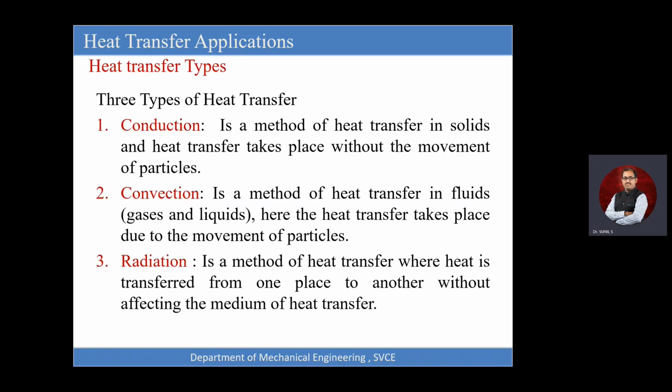There are three modes as we discussed. One is conduction. It is a method of heat transfer in solids only, right? Wherever there are free electrons, they are called good conductors of heat. You may ask the next question, why can't wood conduct? There are no free electrons. Only because of lattice vibrations, vibration of molecules, it can transfer the heat only to a little distance. By the time, this will burn up. Correct? This is not a good conductor of heat.